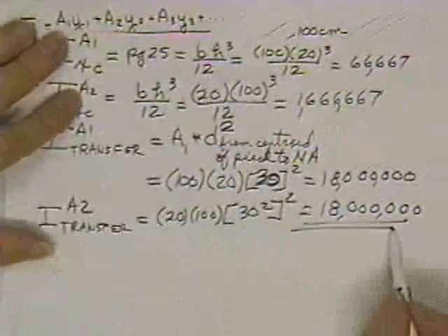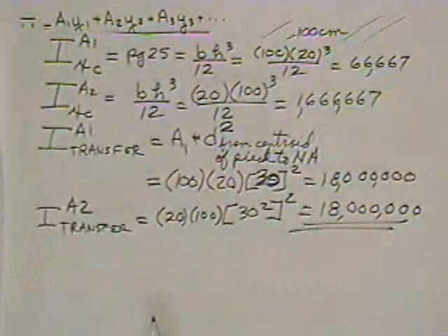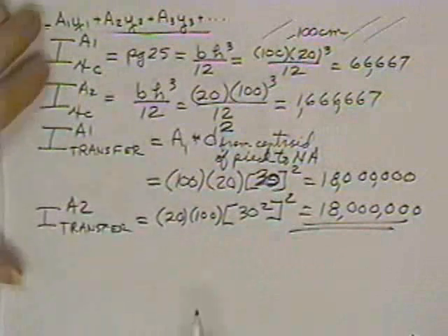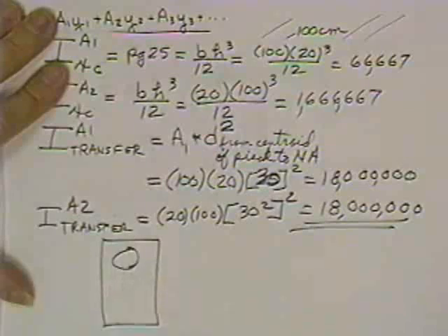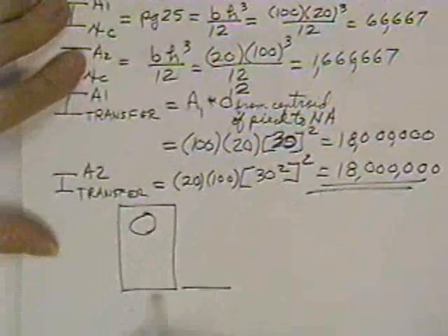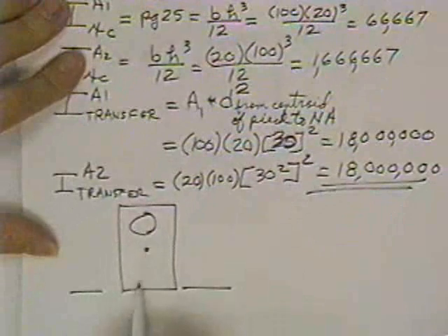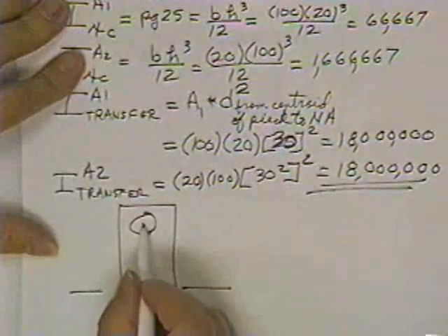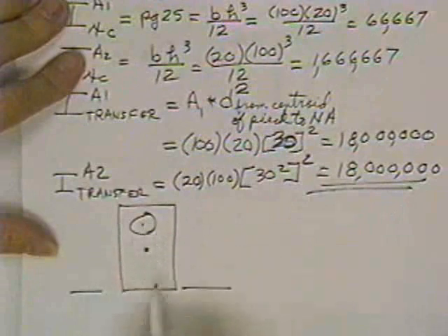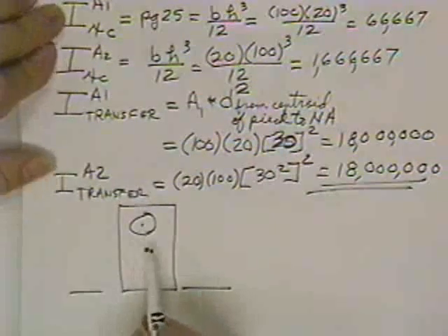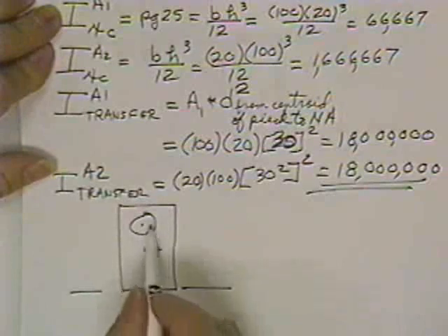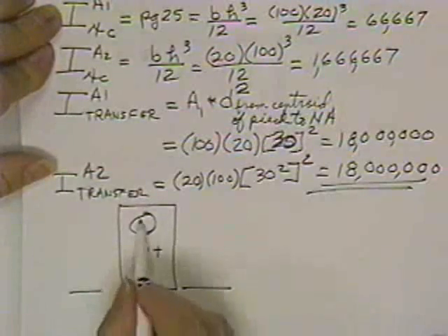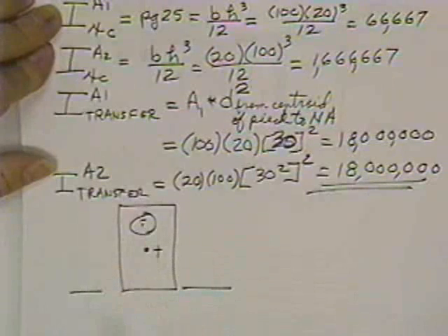All right. And then all you do is you add them all up. They'll always be positive unless the area is a hole, like a missing piece. So if somebody gave you this, you would draw a reference axis, you would take area 1 as a positive area, then you take this hole as a minus area, and you'd solve for where the centroid is. When you did the moments of inertia of each piece by itself, this would be a positive area, and therefore a positive moment of inertia. This one would contribute a negative.